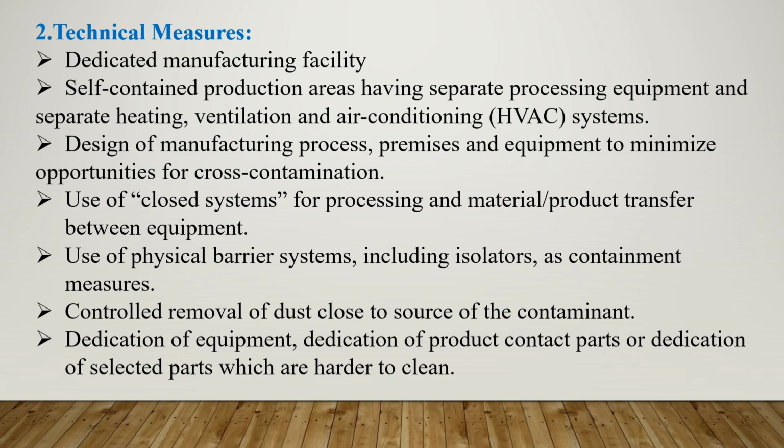Then use of physical barrier systems, then controlled removal of dust close to the source of contaminant, then dedication of equipment, dedication of product contact parts, or dedication of selected parts which are harder to clean.